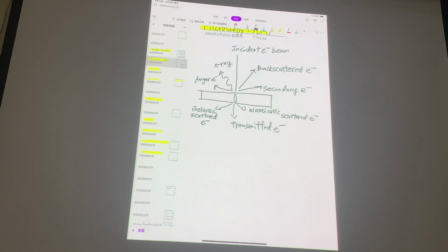So one of the things that I think is really useful information, particularly for you when you use SEM, is that you often need to recognize it when you do EDS. I'm sure everybody in this room has done EDS in one way or another, right? And you need to be cognizant of the penetration depth EDS can reach, right?